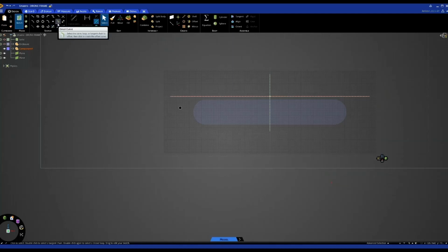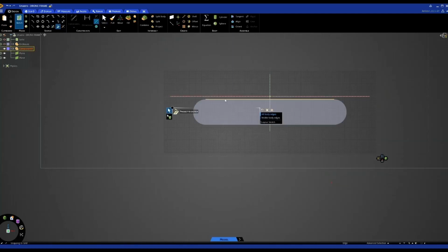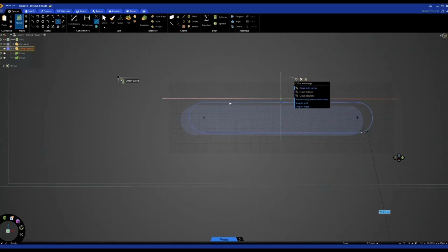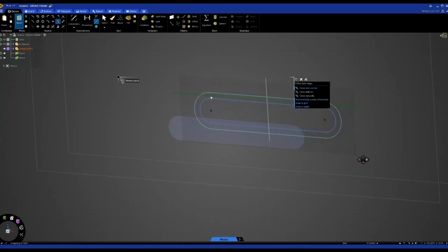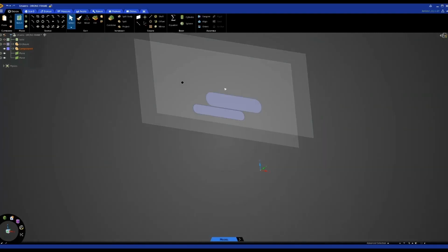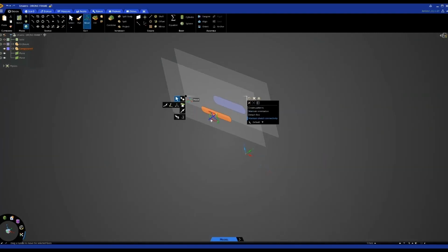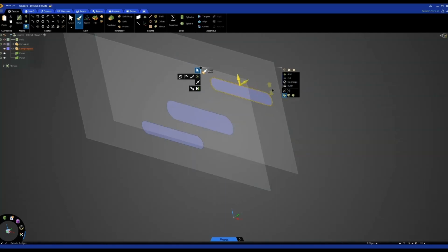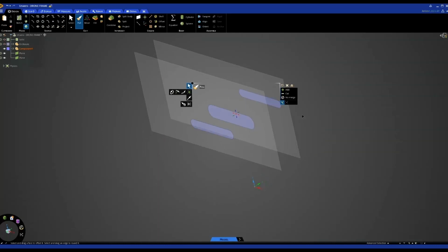To do that, I'll just project this onto my sketch grid, and I'll use my offset curve tool to offset these by, I don't know, 10 mil, let's say. So that's my neck shape. Delete these two here. And then I'm going to use my move tool to move this one maybe to the back. And using my pull tool, I'll make this just ever so slightly smaller. So I'm just doing some basic modeling here. So that might be the profile of my new drone.